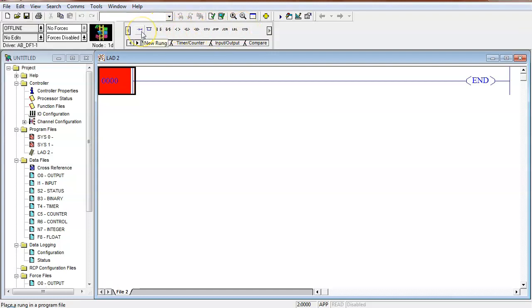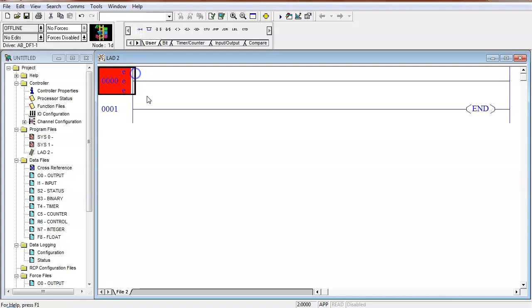When I click on that, right now your user up here has probably got a lot less than mine's got in there. Like I said, I'll show you later on how to add that. But this right here, if you don't know what it does, just put your mouse over it and it'll come up. What does it say? It says new rung. So I'm going to just grab that and pull it down. And notice it becomes rung 0.